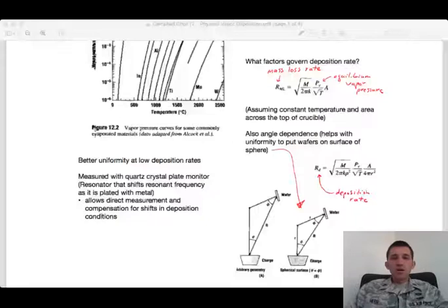And so how fast do you build up coatings? Well, first of all, you need to ask, how fast do I eject the mass from the charge, right? Here we have an expression that was developed by Campbell. This is kind of the net result of a couple of different assumptions. But you see here the factors that go into the rate of mass loss from the charge. Obviously the molecular weight of the atom is going to dictate this, because every time you lose an atom, if it's a heavy atom, you lose more mass.